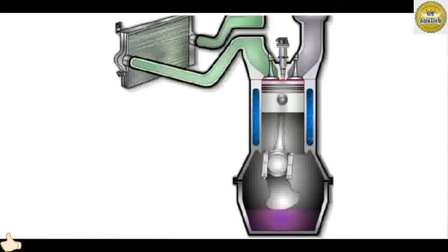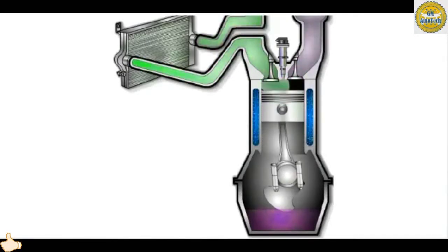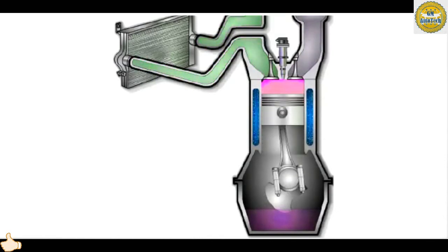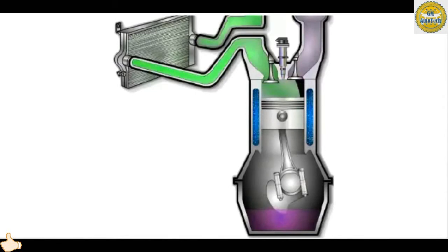In this lesson, you will learn that diesel and gasoline engines have similarities and differences. Although diesel engines have a higher compression ratio, different air induction system, and use different fuels than their gasoline counterparts, they both use the same 4 strokes. In this lesson, you will take a closer look at each of those 4 strokes.